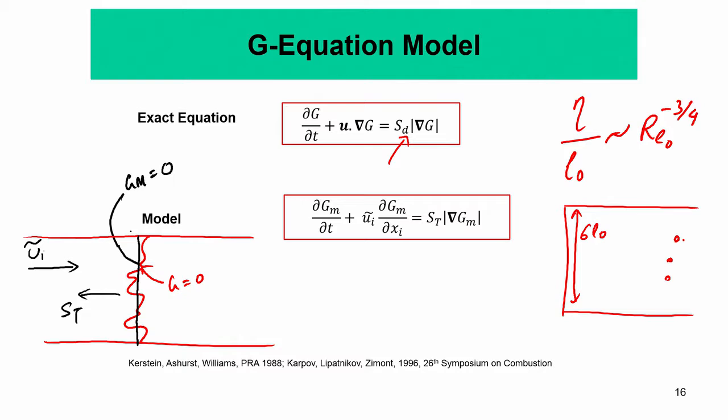than the planar laminar surface area. It will essentially consume a lot more of the fuel air mixture than a planar laminar flame can consume, and as a result the resultant speed with which it will move is given by this turbulent flame speed, and it will be much greater than the planar laminar flame speed. Okay. So, this is the thing.